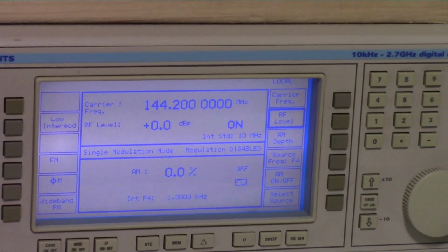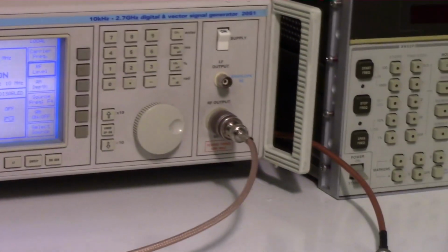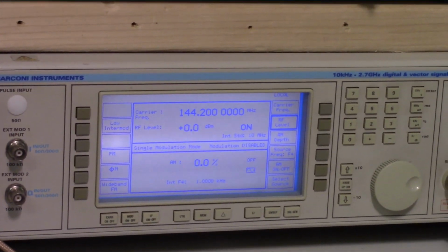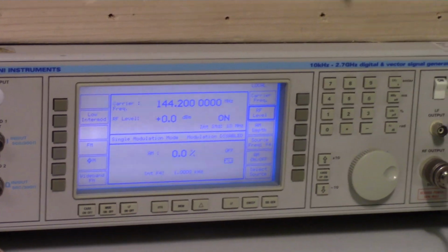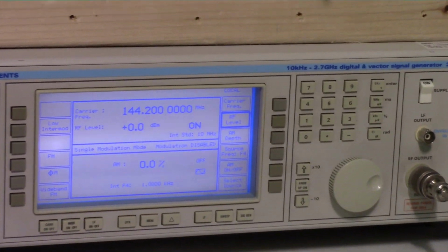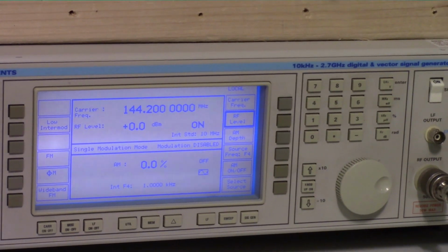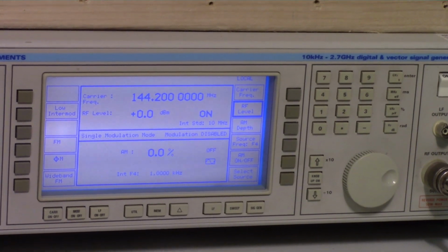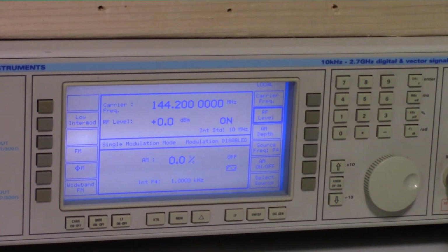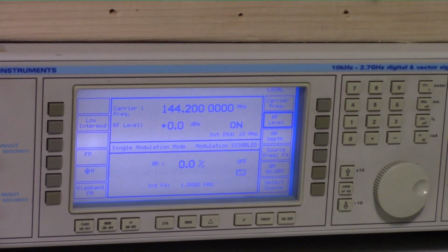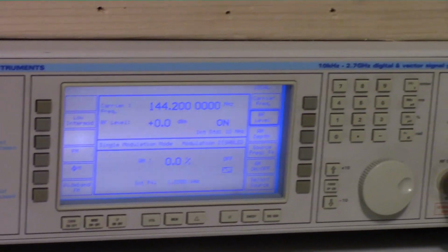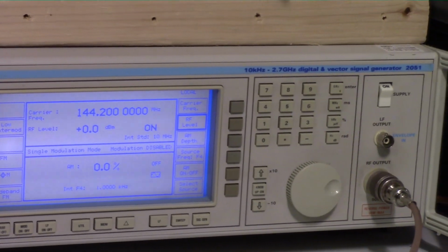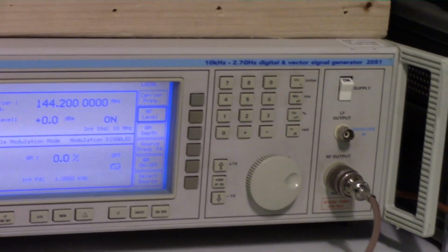So the first thing that you want to do, realize that the amplitude accuracy of your signal generator is what's going to be very important here. You want to be sure that when your signal generator is set to minus 100 dBm, it is actually minus 100 dBm. Or if you put it to minus 130 dBm, that it's actually minus 130. Those numbers are going to be used to determine the actual MDS, or the sensitivity of the receiver. So you have to have an accurate signal generator where you know the amplitude.